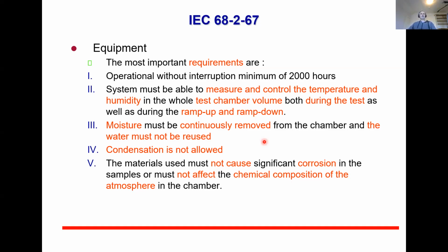The moisture which you use must be continuously removed. You cannot recycle the water, because if some impurities are dissolving from your product, then the amount of these impurities would accumulate during the test, and then you would start seeing electrochemical effects.